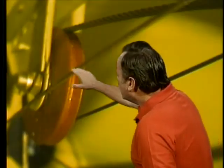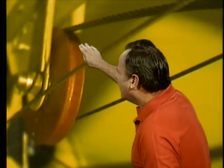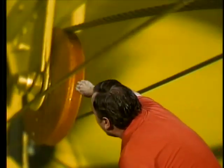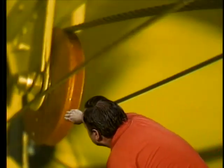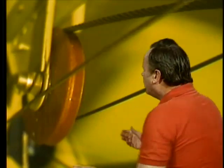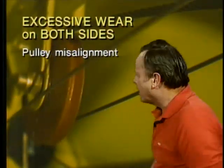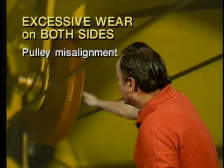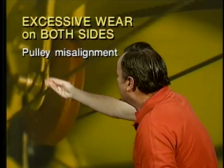Now let's assume you're out in the field as a working mechanic and you are inspecting a control cable pulley like this one right here, and you check the pulley groove and you see excessive wear on both sides of the groove. Now, you look in here and you see a lot of wear inside that groove on both sides. What would that tell you? And the answer is it would tell you that you have pulley misalignment. It's not lined up properly. So excessive wear on both sides of the groove of a control cable pulley would tell you that you have pulley misalignment.